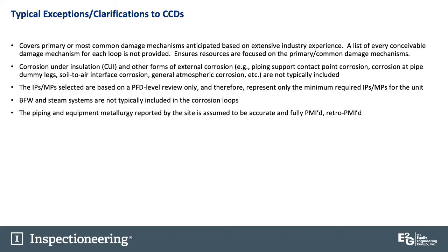The injection mix points selected are based on PFD level reviews only. This is more when you have external resources assisting you with this. And at some point, you should go into a P&ID level review to make sure you got everything included. Boiler feed water and steam systems are not typically included in the corrosion loops. And the piping and equipment metallurgy reported by the site is assumed to be accurate and fully PMI'd and retro PMI'd.